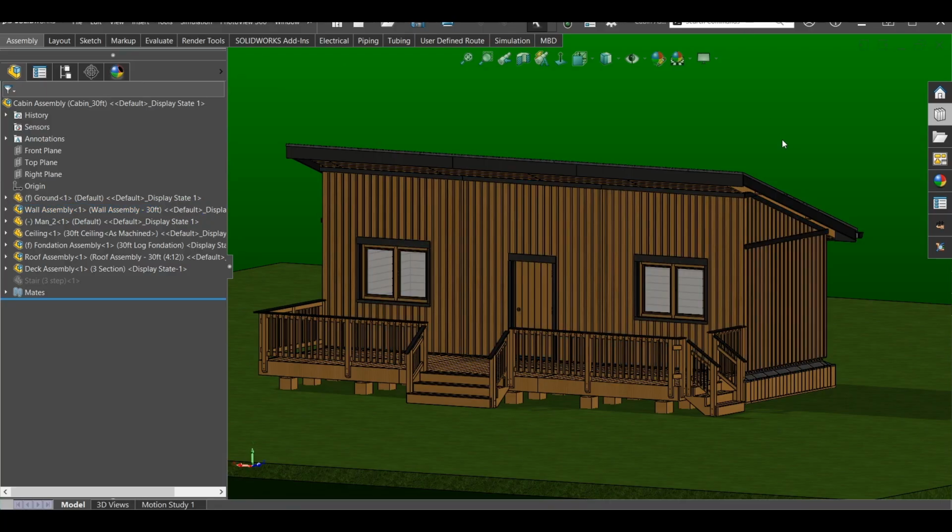Everything is dimensional lumber, so 2x4. Windows are 2x3s. A lot of 1x4, 1x6. I think the entire facade is 1x6. The skirt is 1x6, 2x8s for the structure.